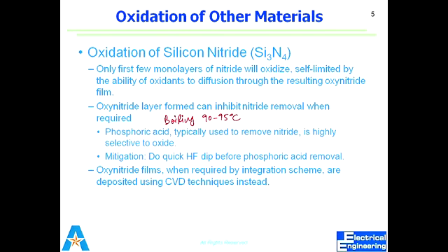Nitride is actually the second option in industry after oxide, but oxide is still better than silicon nitride. Yes. But as I told you, in some cases silicon nitride comes into play. It's a better option as compared to silicon dioxide. It depends again on our process, what protocol we are following.